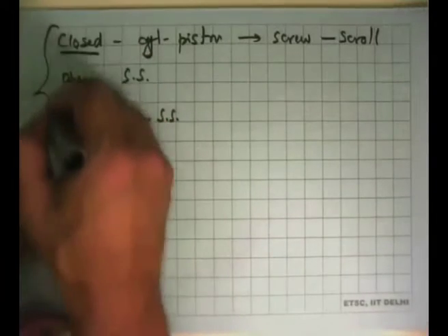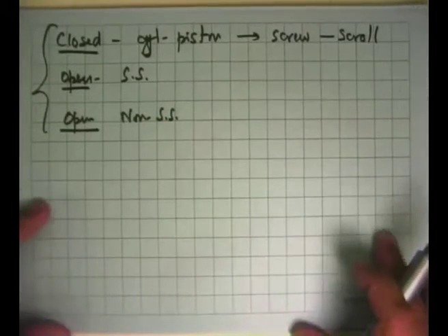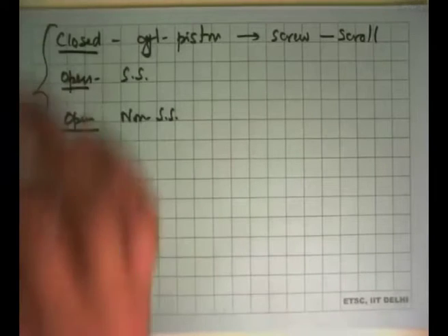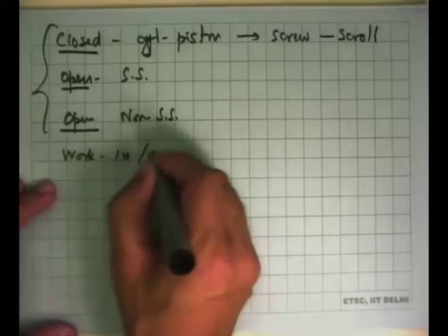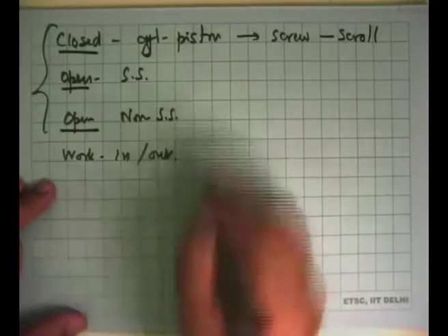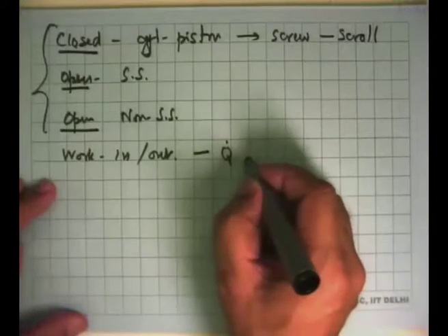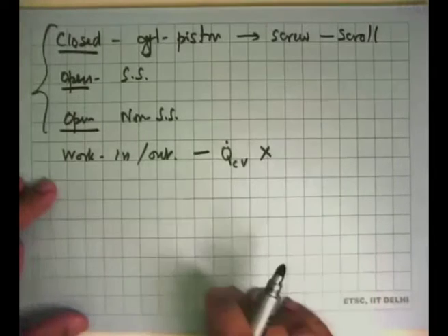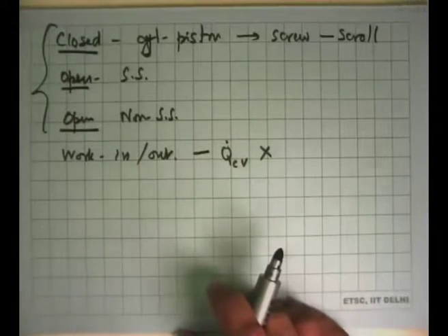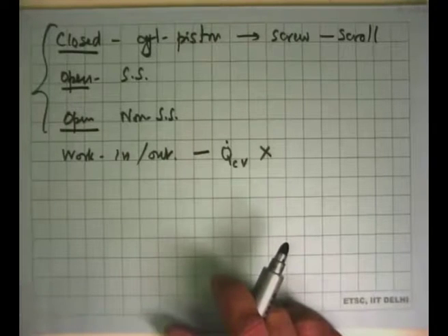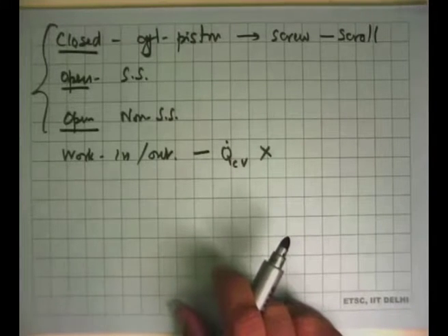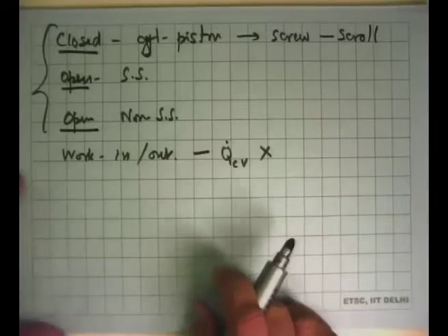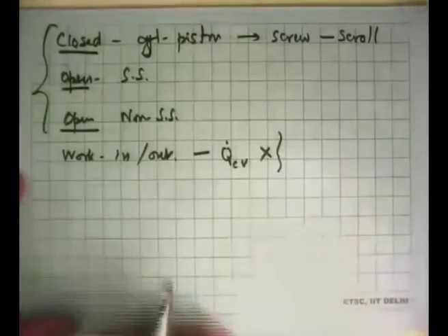And during this discussion we said that depending on the type of machine we are looking at, this machine has certain characteristics. For example, we said that if it is a work in or work out type of machine, then Q dot is not possible. We cannot make a turbine where you can cool or heat it and at the same time get the working substance to expand. Same thing with the compressor: if you say make me a compressor where I will compress it and at the same time heat it also, such a machine cannot be made. So we are now seeing certain restrictions on what happens.